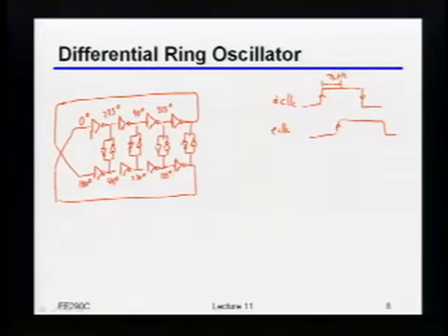All right, so this is indeed actually a fairly common technique. As we were implying a second ago, because I want to use both the 0 degree and the 90 degree, and I really want them to be 0 and 90 degrees, I really have to make things match, right? So all of the level shifting that I do on this stage, I better also do here, and typically you almost always better do it here and here also, because if you don't, you're likely to get some mismatch, okay?